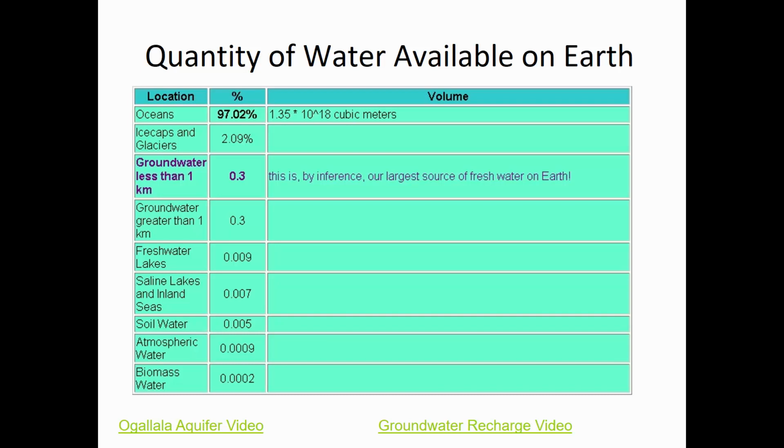They can have like a fine mesh down below. It's not just a pipe with no holes in it. It's a pipe that has serrations and like a fine screen on the outside to allow the water to go through, but not to allow the soil particles inside the aquifer to fall into the well casing.